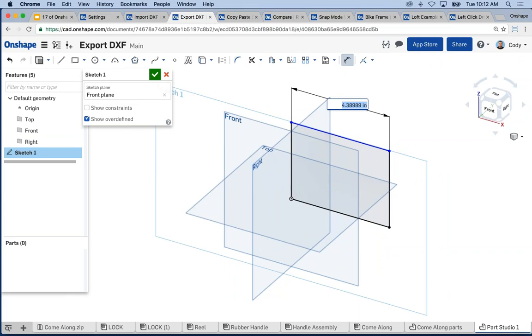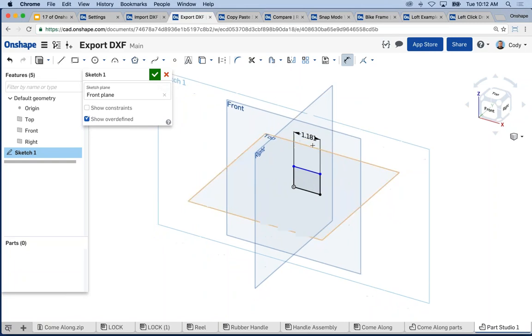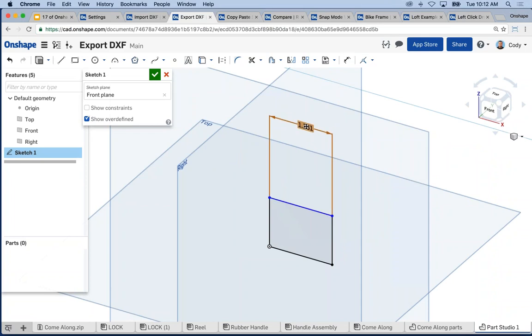But there may be scenarios where you need to change units. Maybe not for the entire document, but for an individual dimensions. There might be scenarios where I largely design in inches, but I need a few metric dimensions, or vice versa, right? The important thing I wanted to point out, you can enter mixed units. So I can say 30 mm, and it will do the conversion for me in the actual dimension dial, right? So just keep in mind, it's not visually changing it, but the metric value is there. So it's just doing the conversion for me.